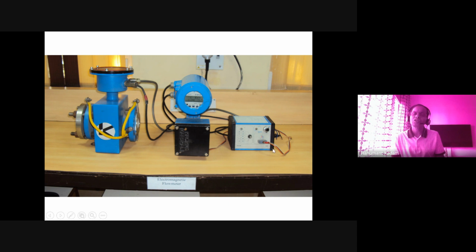And you see this is the simulator. Simulator means, as you know, you have to calibrate the flow. So actually sensor calibration is one part, meaning inside the sensor whether they are sensing properly. Suppose it is full of water, so it's a steady flow. Steady flow means some reading has to be shown here. And when the conductor is moving, velocity is increasing, then your reading will change. So at least you can have a zero reading here, steady flow, or your zero and span. Zero you can get here because you are fully conducting with the full of water. So this is the one part.